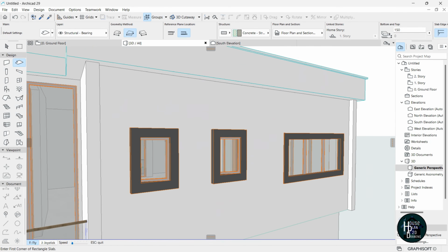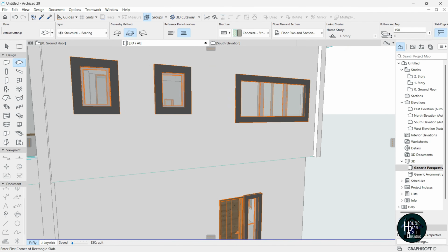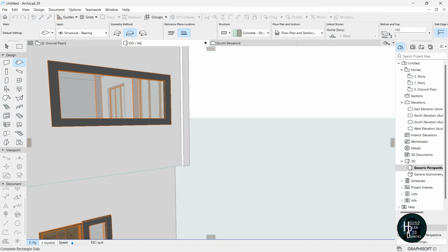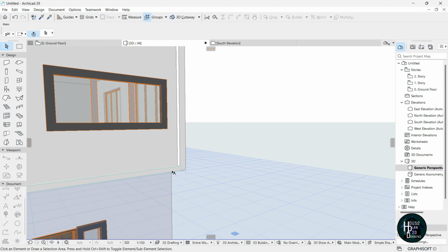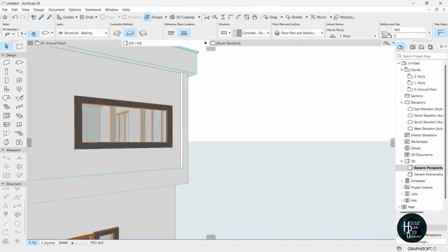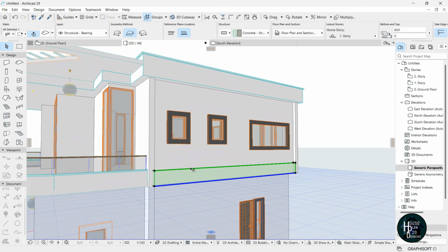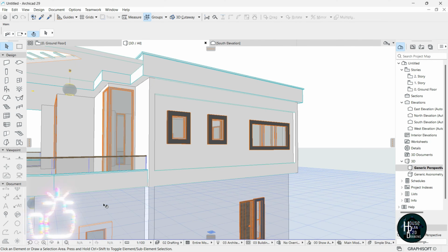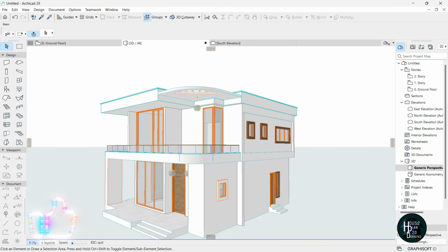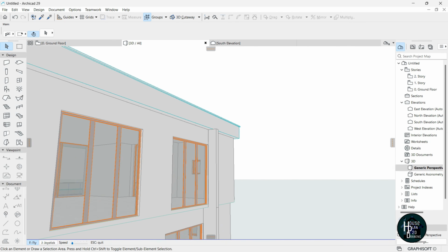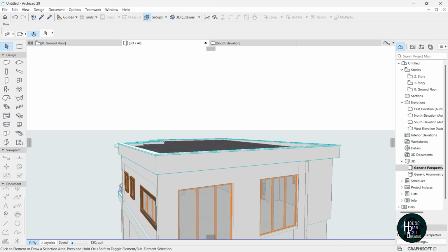Then what you want to do next is just click the edge there. All right, once you finish doing that, come to the side here and just select. Okay, click this, click on the side here and just try and stretch the height to be something around 600. Click enter on the keyboard, and you also want to do the same thing by holding down Ctrl Shift D. Click this and move it up, then press escape on the keyboard, and that's how I went about that new and simple design. Okay, so there's not really any fuss about designing stuff like this.